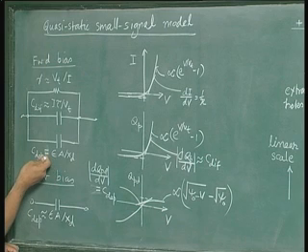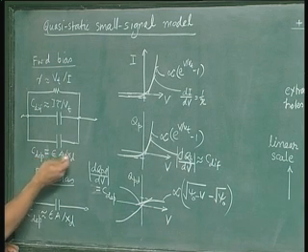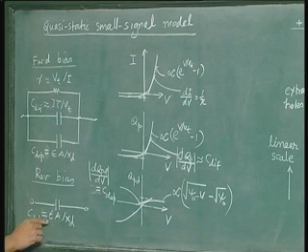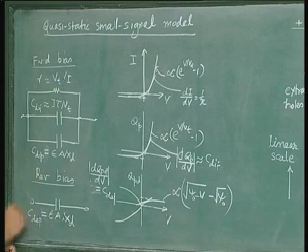Okay, this is an incremental capacitance. It is like a parallel plate capacitor. The incremental charges are separated by the distance xd. For reverse bias, we should put exactly equal to sign. The depletion capacitance is again given by epsilon A by xd. Here xd goes on expanding, so depletion capacitance falls.